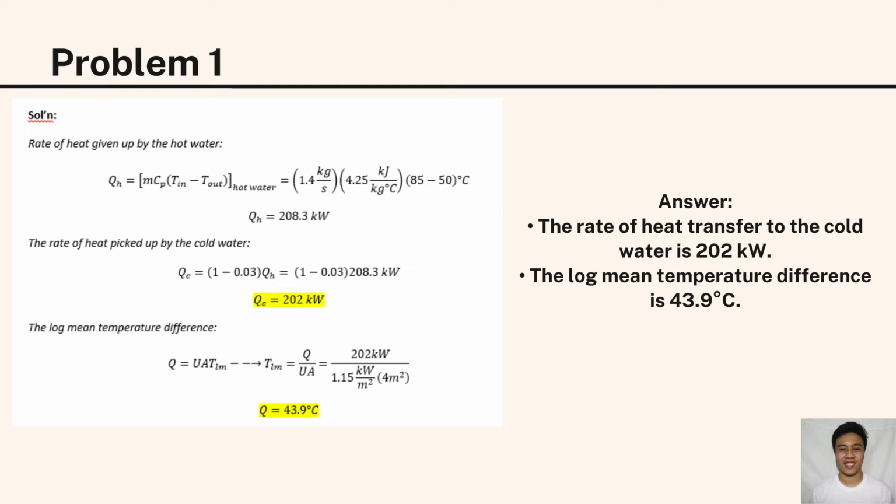So the answer to the problem is the rate of heat transfer to the cold water is 202 kilowatts, and the log mean temperature difference is 43.9 degrees Celsius.